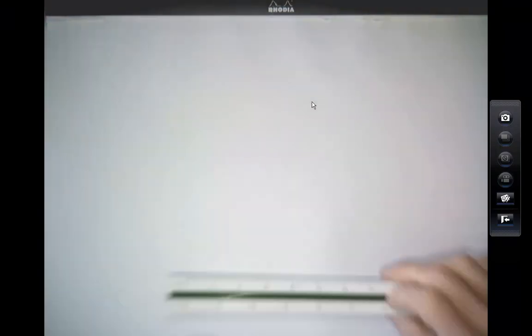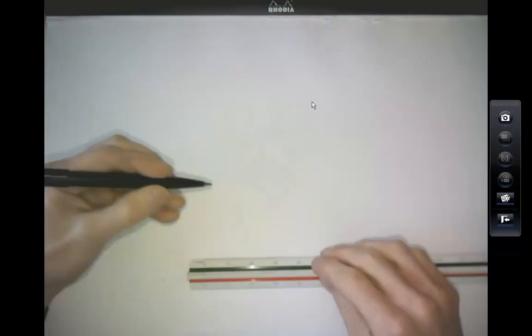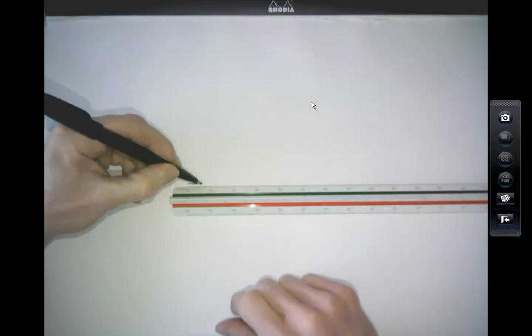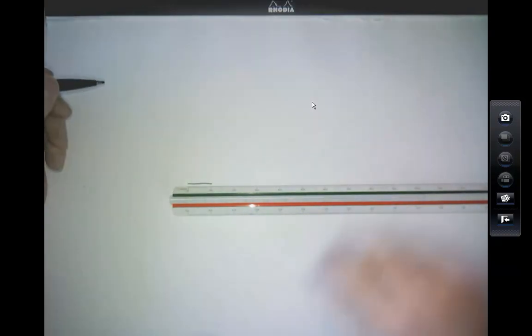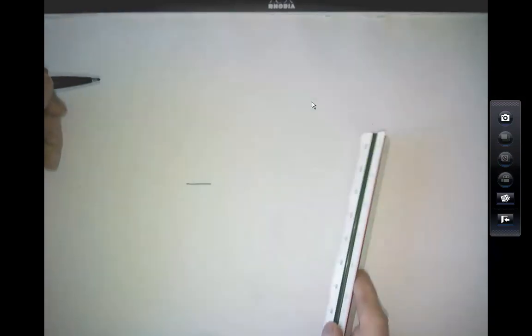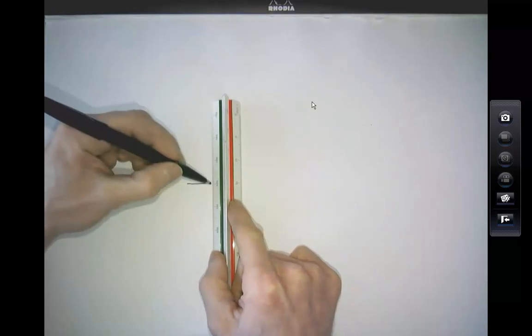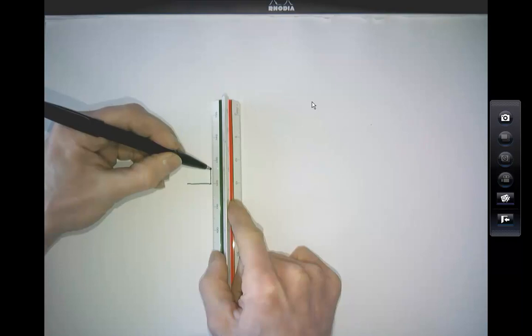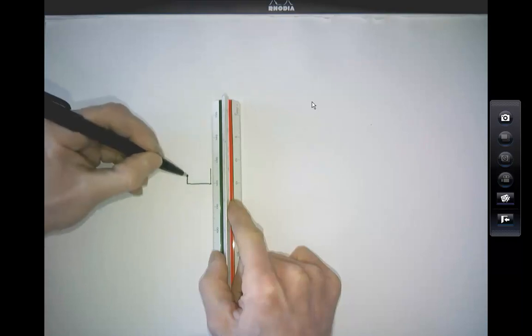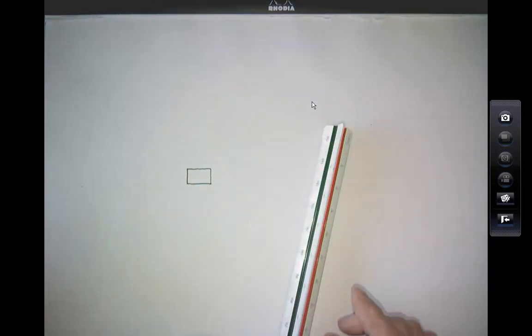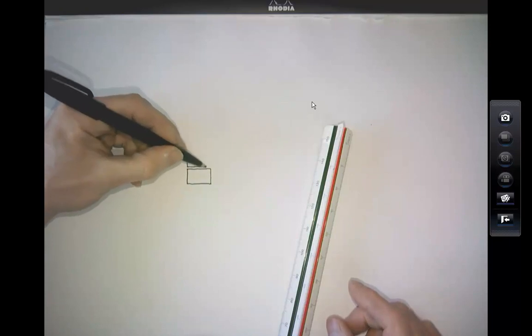Right. So we're going to look at the ground condition. And as always, we'll start drawing something we know. I'm going to draw it 1 to 5. Let's just go up here. We know we've got bricks. So there's a brick width. Try and focus that a bit. Come on. There's a brick. It's 102mm wide and it's 65 high. So we'll just measure that one just to make sure that everything else is about right. So we know we've got some bricks. I'm just going to draw some more.